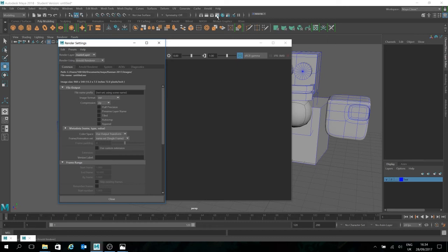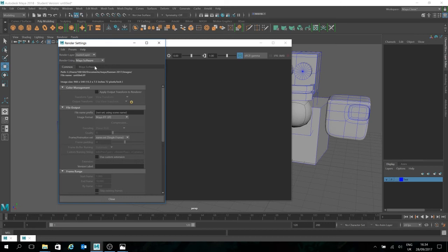You click on this gear, these 4 parts here, touch the first one or the second one. The first one is to view what you have rendered. The second one is to render, and beside the hypershade is the settings. For now, don't go for Untitled render, just go for software. Untitled render is going to confuse you even further, so don't touch that yet. You want to explore, you can explore, please do so, but the basic one is Maya software. Click on this Maya software, go for the common, master layer.